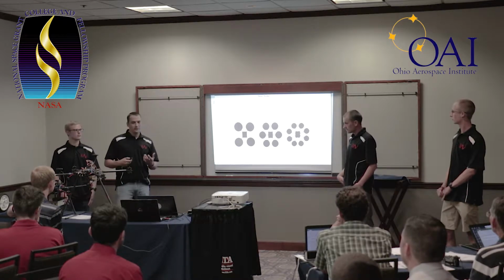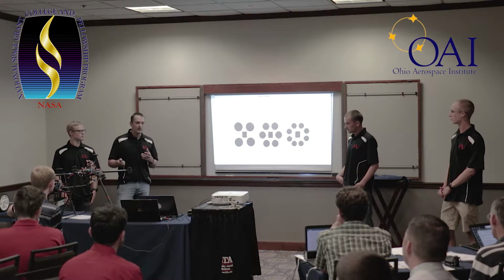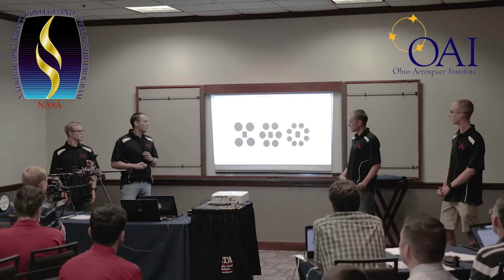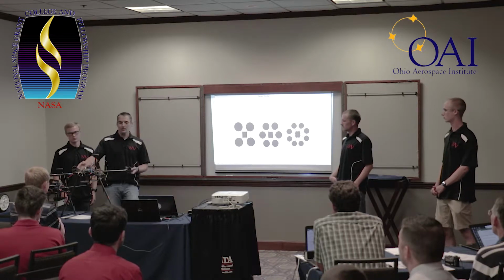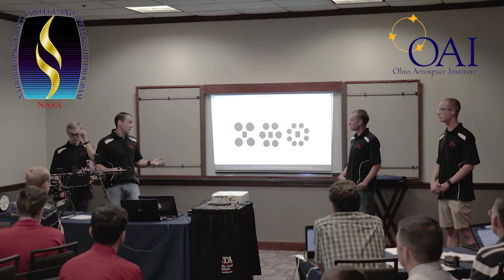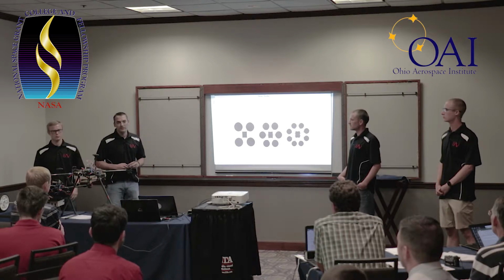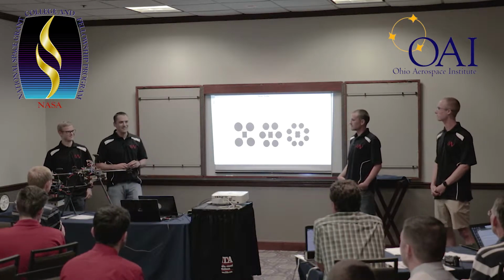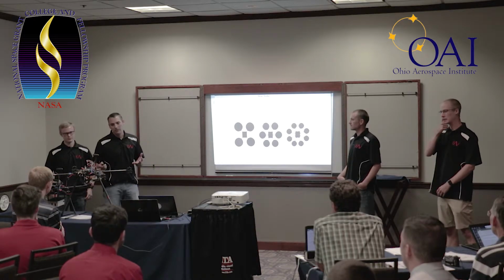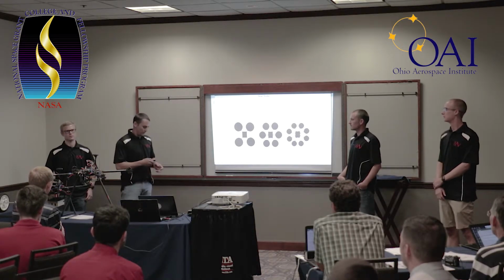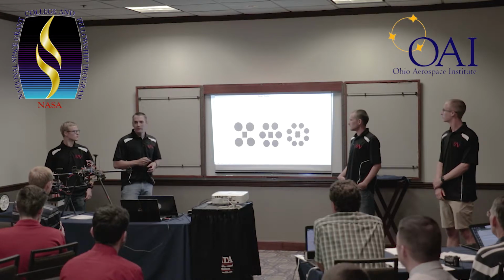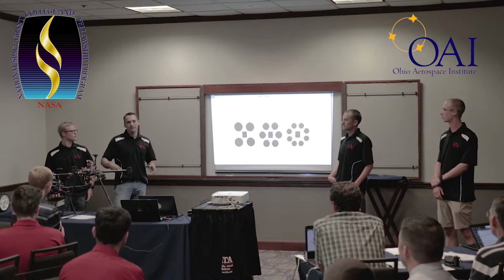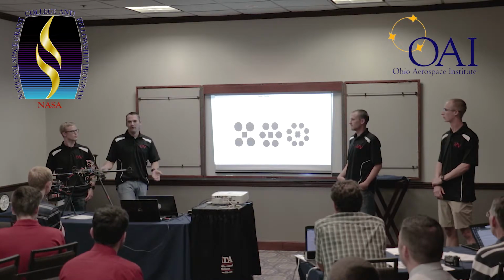So what we were interested in doing is finding out what the most optimum setup would be. Turns out, a quad that's stacked, as you see it here with motors top and bottom, is actually the most efficient setup. It provides some pretty serious fault tolerance, which we'll talk about in a second, because we sadly found that out. Ideally, it provides optimal efficiency, and you don't have to worry about additional arms, additional components to attach the arms, additional motor mounts. You're utilizing the same componentry you have for 4 motors, but you're adding 4 more motors for free on the bottom side.